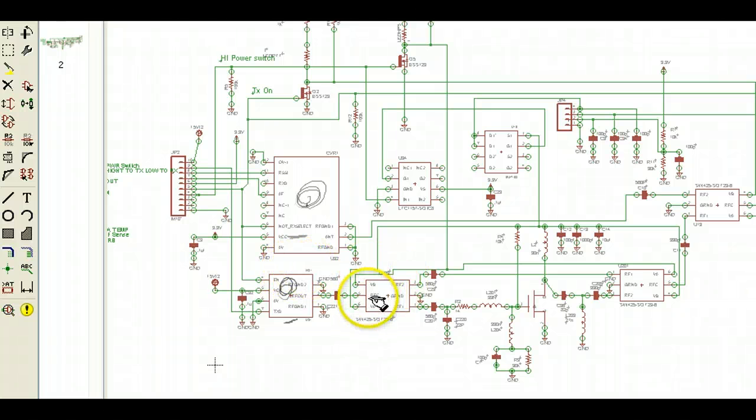This is a switch. We've talked about that, and it can be modeled by just a plain old physical switch. The voltages on this side and this side control it. A high here and a low here will make this switch do this. If you put a low here and a high here, it'll make this switch do this. So this is just a plain old solid state switch.